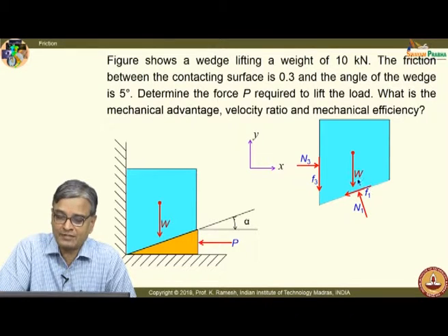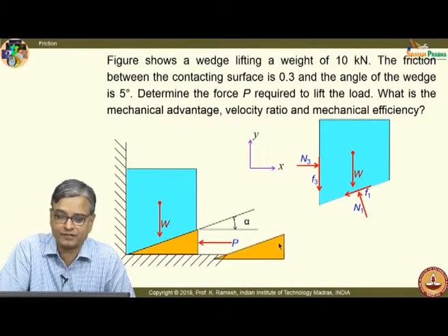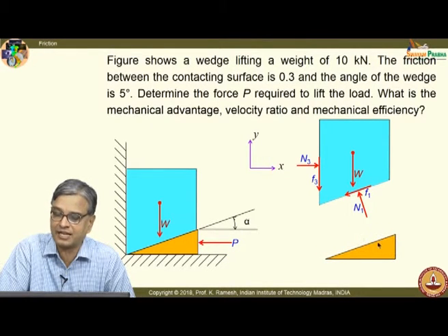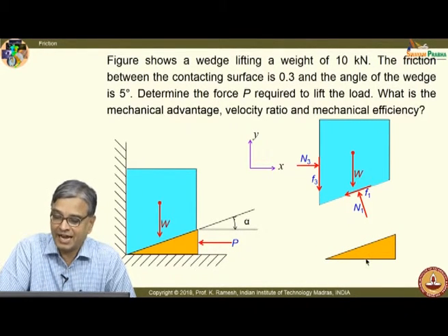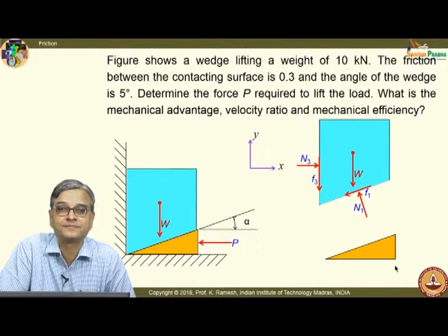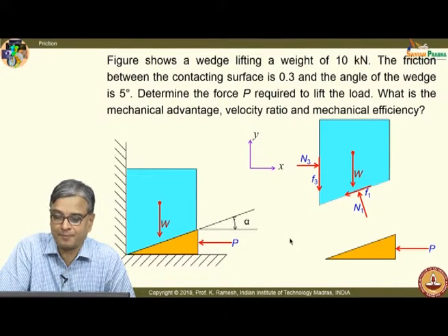And once I have assumed this force direction, automatically the direction of force on the wedge is fixed, at least in this surface. And this surface, what way the friction would be? Because I am driving this like this, the friction will try to oppose this. Okay. I have this force which is applied.